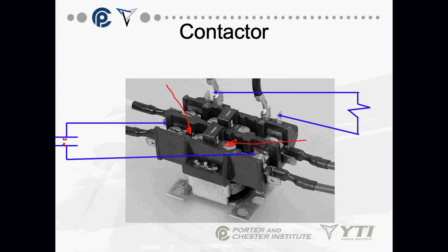Contactors in an air conditioning system in your part of the country have probably a lifespan of 5 years. About at 5 years, you're going to start seeing some burn marks here. It's going to start looking like a lot of carbon buildup. Carbon is an insulator. Believe it or not, this $60 part, that's the customer price, can actually take out a $500 compressor if these contacts start building up too much carbon.